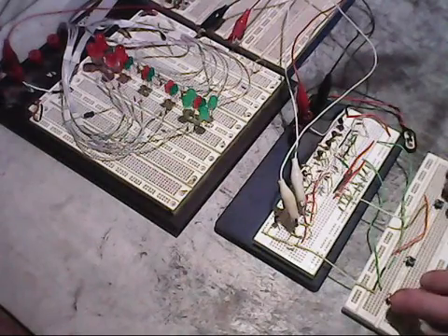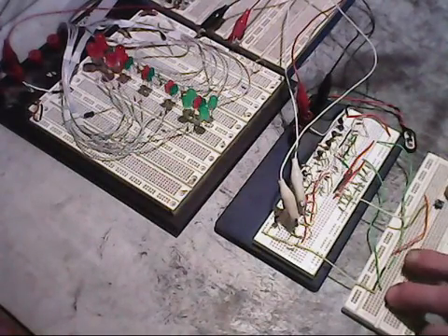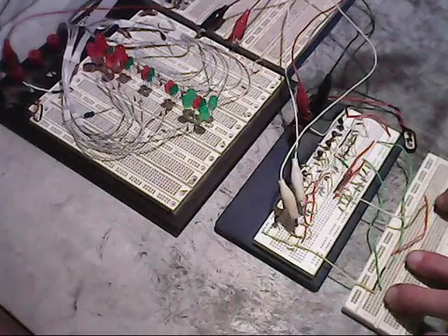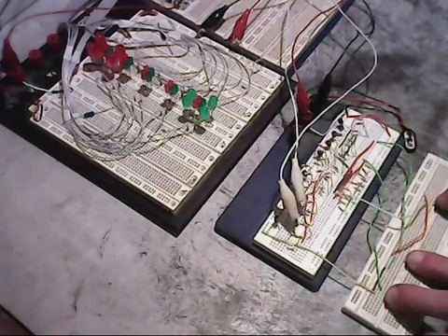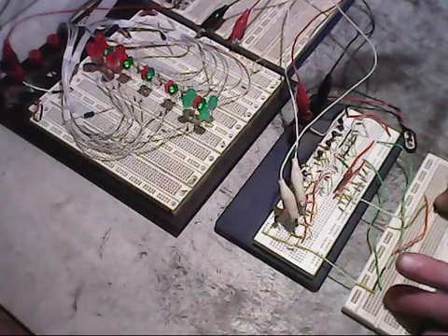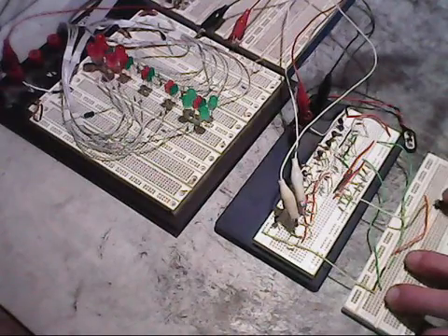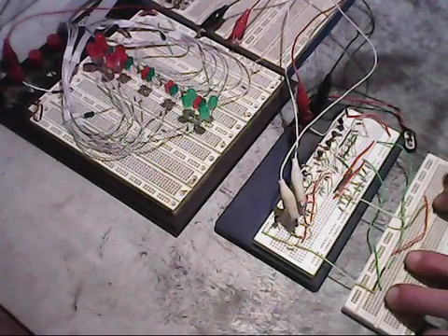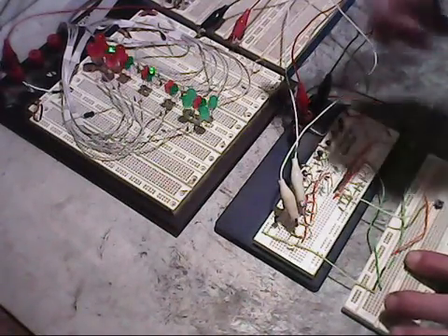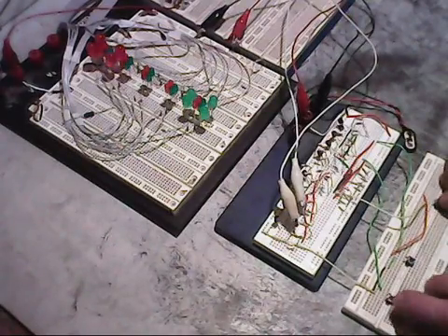Now here we go to the exclusive OR function. If I hit the left and the right both together, and I hit the fire button, nothing happens. If I let go of the right side, now the left side goes on. If I put them both down again, nothing. I let go of the left side, and now we have the right side working. So the exclusive OR gate is working.